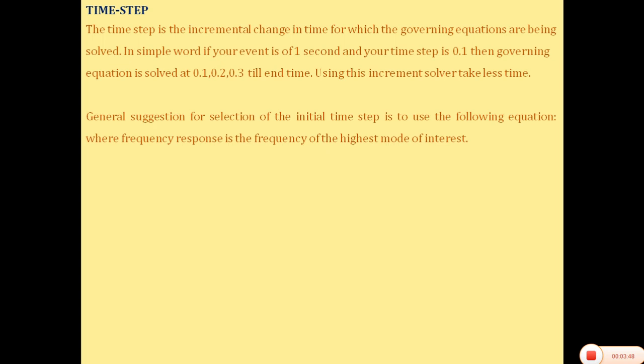Otherwise, if we take the same thing into explicit and we are not using the time step, then the solver will take a very long time and it requires very heavy hardware also. Every software has various methods to calculate the time step. When velocity and acceleration problems arise, we will see another way to calculate the time step, but today we are going to see the transient structural analysis.